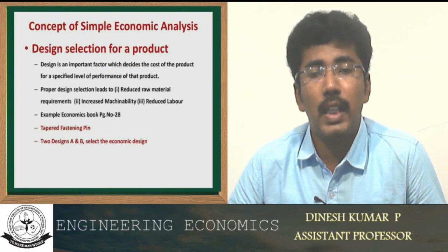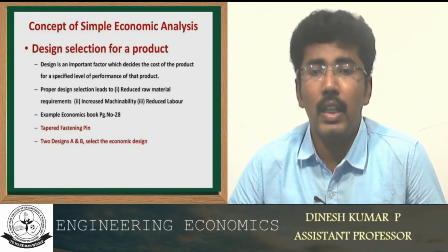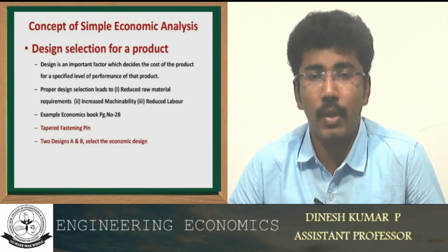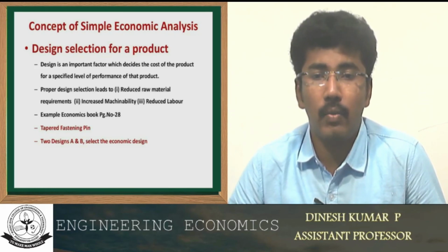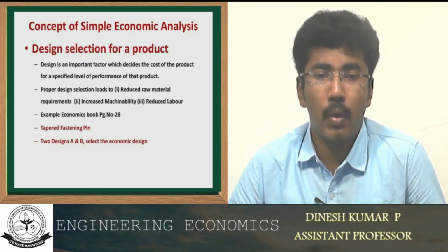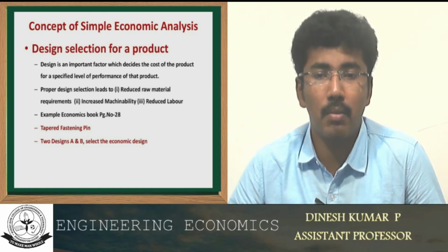Next, the design selection for a product. Design is an important factor which decides the cost of the product. For a specified level of performance of the product, proper design selection leads to reduced raw material requirements, increased machinability, and reduced labor.